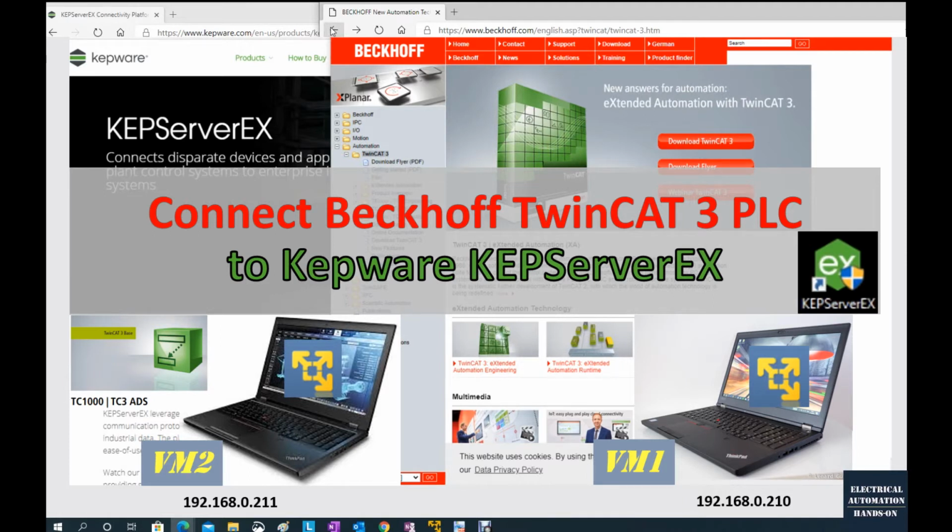So if the KEPServerEX is installed standalone on one laptop, you have to install the ADS, the Beckhoff driver, onto this laptop. Otherwise, you cannot communicate with a remote Beckhoff controller. So you have to install the ADS driver with this KEPServerEX. That's why I wanted to show this video.